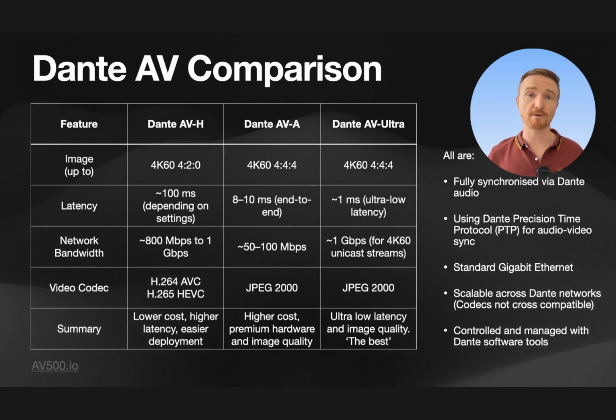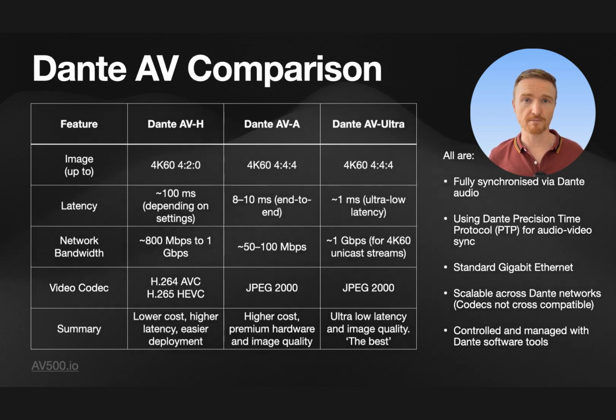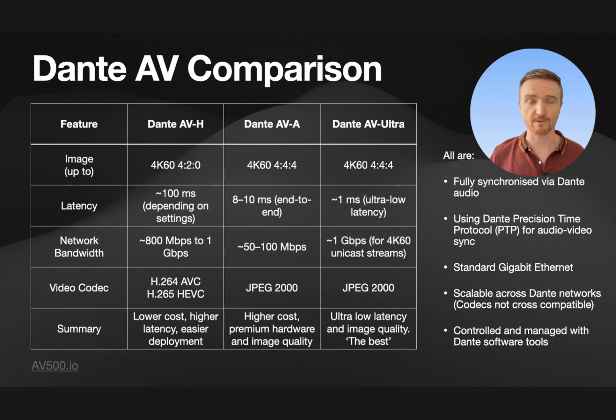Despite being a licensed proprietary technology controlled by a single company, Dante has been exceedingly successful in implementing its audio-based protocol into many products across many different manufacturers. One of the advantages of Dante coming from an audio-first platform is that the synchronization is done in a PTP-style, sample-accurate sub-millisecond precision, where other platforms like NDI and SDVoE come from a more video-first approach. Their synchronization is more Genlock-style, frame-accurate, which is fine for most applications, but it's an important distinction to understand.